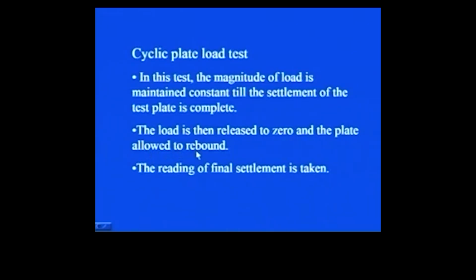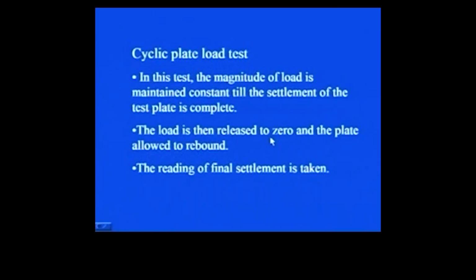So first, once you have loaded to some particular load, then you have to unload it. After loading, let us say for the first cycle, you have to maintain that load till the test plate stops settling. Then from that point of time, you go on withdrawing the load from the test plate. That means you have to unload the test plate. In that process you will be removing the load in some steps, and the load will be released to 0, and